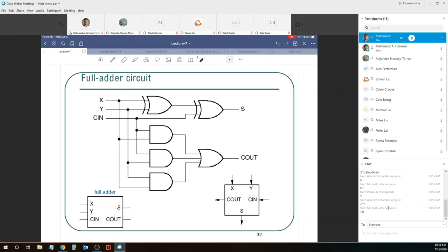So we have looked at the expressions as well. We are just drawing the logic diagram for this over here. And again, C out is 2 gate delays. First level, all of them happen at the same time, and then the second level. For some, because it depends on carry in from the previous stage, we need to worry about the same thing again, C out.